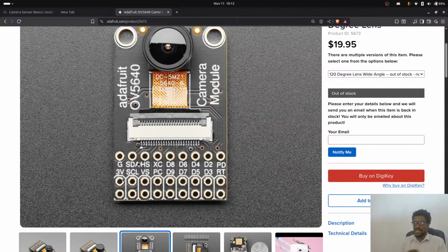So telling the camera, start taking frames, set the exposure to this, set the gain to this, set it black and white, set it infrared, whichever one you want, and such. And then there's an H sync and a V sync, which is a signal that displays you've either sampled a whole line or you've sampled a frame. We'll get to this later. And then there's a master clock, which is the X clock, and there's a P clock, which is the peripheral clock. It is for synchronization between the camera and the host processor.